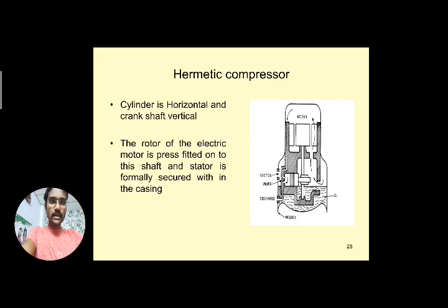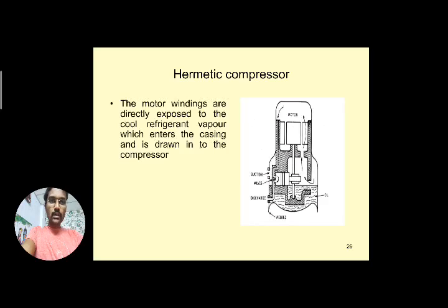So it is tightly secured at the sides. The stator and the rotors will be here at the top of the casing, you can see here. Now the motor windings are directly exposed to the cool refrigerant vapor. Whatever vapor is entering the compressor, here it is getting exposed to the cool refrigerant vapor, and automatically the cooling will take place with the help of this refrigerant vapor, which enters and is drawn into the compressor.